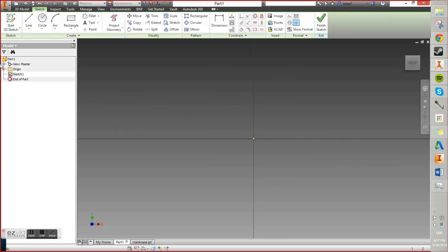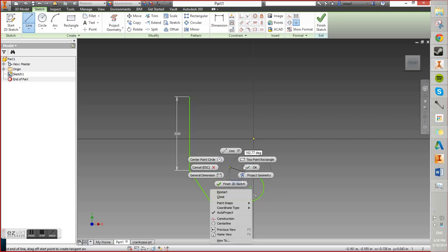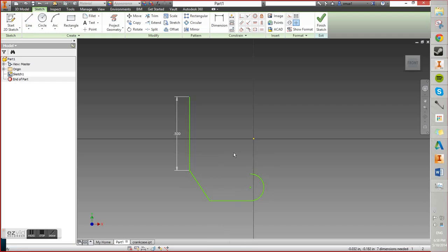And here, let's just explore some of the things the sketch menu has. We can draw lines, just 2 points in space. And there we go. You can hit Tab to cycle through the options and the input boxes to set angles and lengths. And if you just keep clicking off, it'll create lines. And at the end, if you click and hold, you can create arcs. Then to finish, you right click and hit OK, or you hit escape.